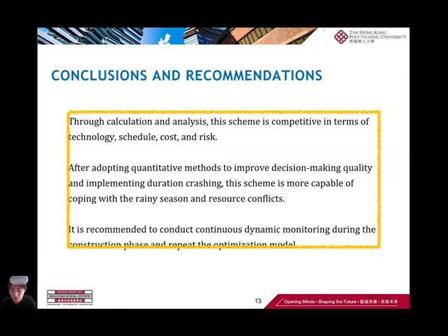We recommend three key actions: strengthen progress monitoring by increasing reporting frequency and integrating real-time site data to prevent schedule slippage; optimize resource allocation, especially for foundation and basement works, to reduce inefficient spending; and implement cost control measures such as reassessing subcontractor productivity and revisiting inaccurate assumptions for high-cost items.